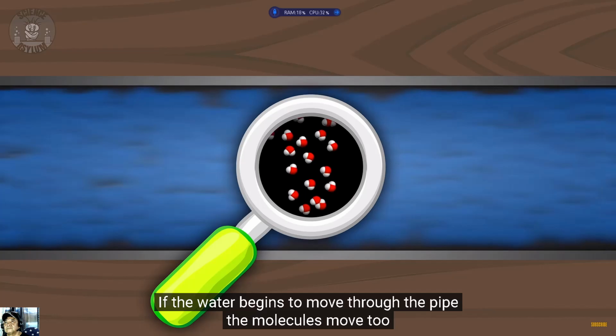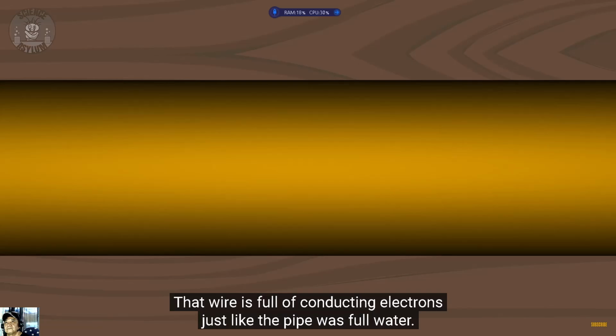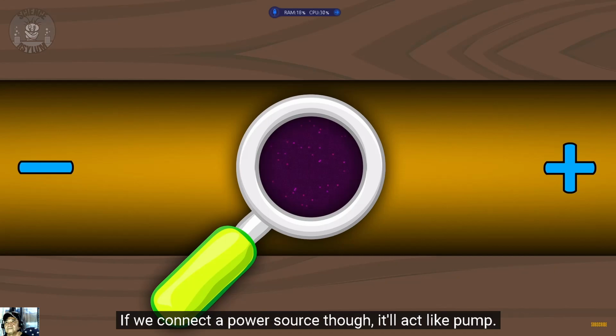They still have the random motion, but they now also have forward motion. A similar thing happens with the charge in a copper wire. That wire is full of conducting electrons, just like the pipe was full of water. Individual electrons are conducting around the copper randomly. If we connect a power source though, it'll act like a pump. The electrons will still have the random motion, but also some forward motion.